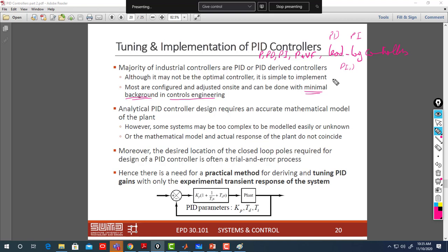Well, to be honest, they are not really coupled. You can control them independently, but they still affect each other. So yeah, some control engineers, when you control a robotic arm, could control it motor by motor, but your system is not going to be as good as if you take the coupling between every link into account.